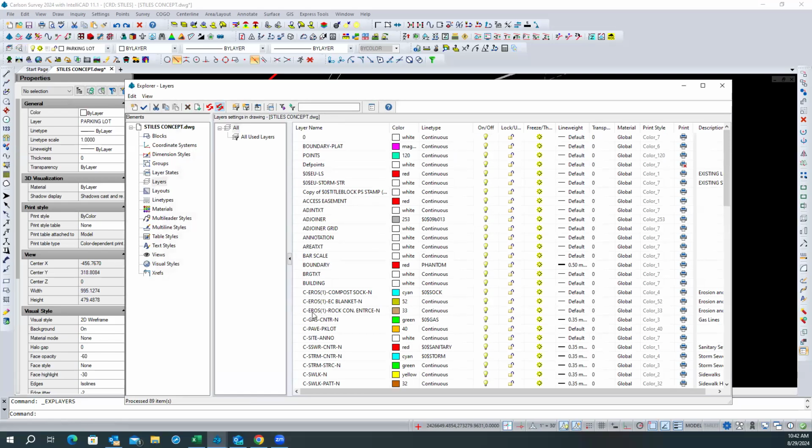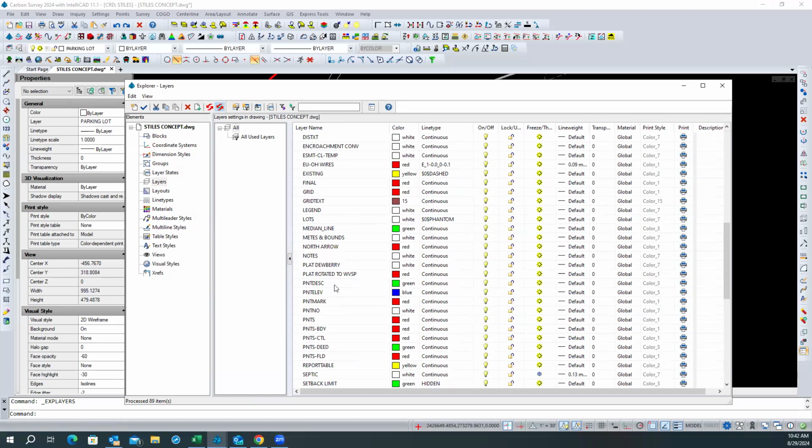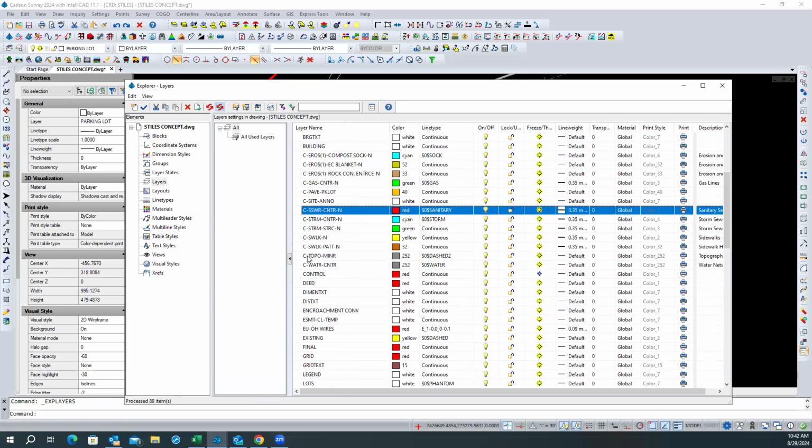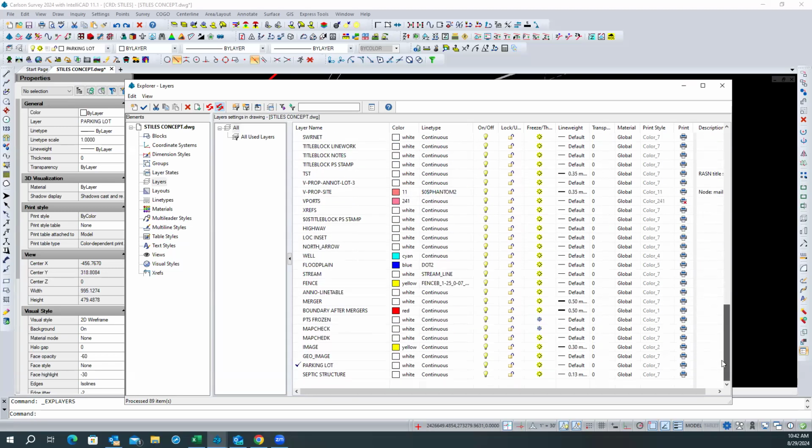So now you're using these layers. We've got C layers, and C is a prefix that generally means civil. And V, you see a couple of these. This drawing I originally took from a Dewberry drawing. That's fine. This is a job I inherited from them. Absolutely fine. I'm just saying, if you ever want to start using some of these national CAD standard naming conventions, this V dash tends to indicate survey, because the structural engineers got in line first and they took the S.